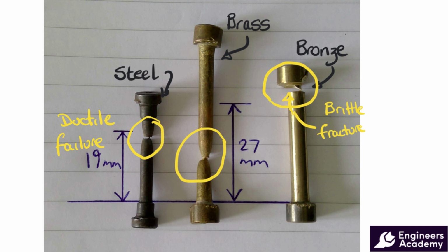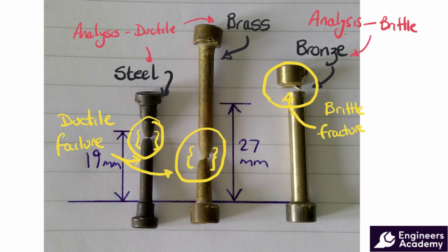The other 2 samples show what we would call ductile failure, where they neck or stretch, having a plastic zone where the material is pulled out before it finally snaps. So the qualitative data here would indicate that the right hand sample is brittle and the other 2 samples on the left hand side are more ductile. We can also see that because of the necking before failure on the 2 left hand samples, they're going to be more plastic in nature than the one on the right hand side, which is obviously going to be quite brittle.